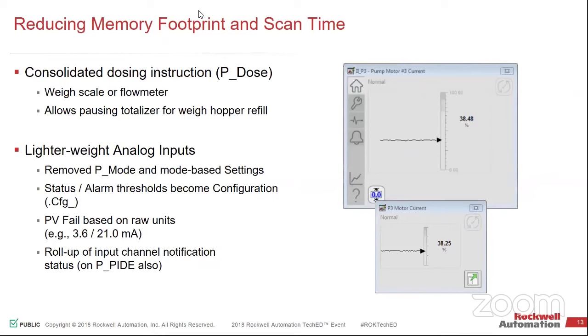So just because the process objects are coming out as part of the system release for the DCS, you can still go back and use them in version 24. Okay? The only requirement is going to be the Factory Talk View version will have to be a version 10. But the actual controller side of it can be pushed back to something older than 31.